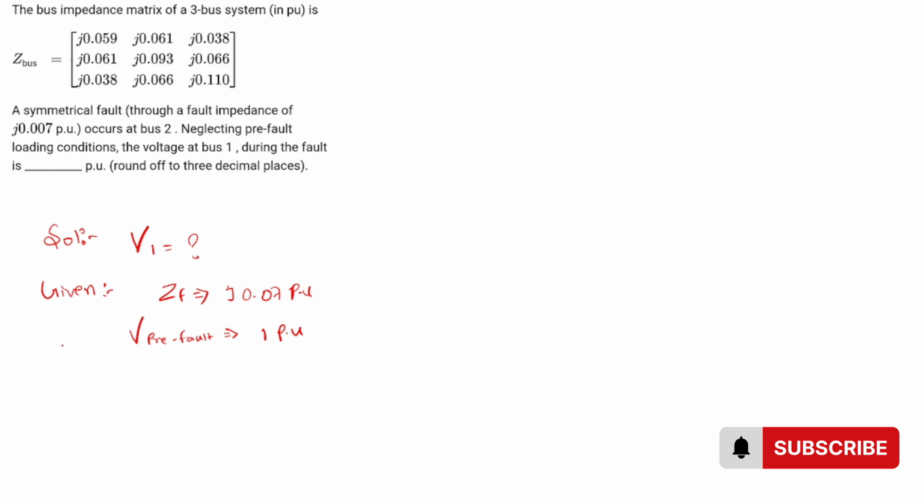So the fault current IF is equal to V pre-fault divided by Z22 plus ZF. Why do we take this? Because of the property of Z bus, IF is equal to Thevenin's voltage divided by Thevenin's impedance. That's why we take this.